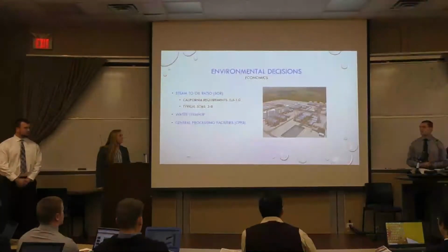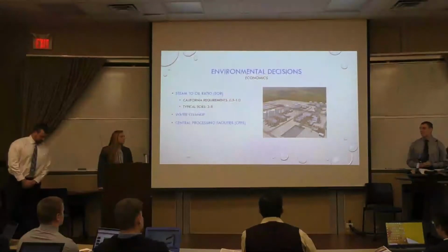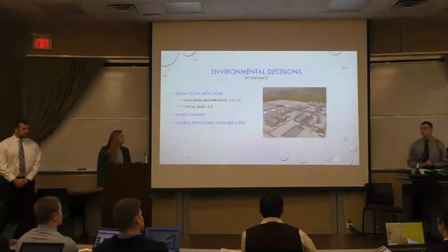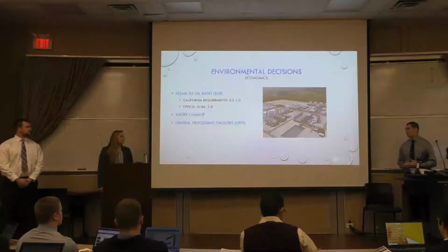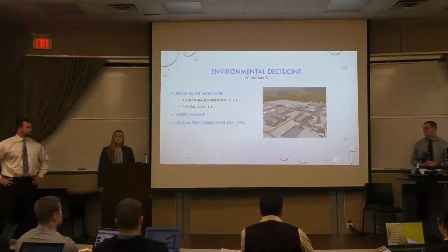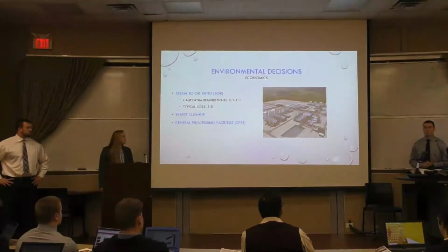It's also important to look at water. Not only the cost to inject water, but the cost to clean it once you get it back, which is kind of a backdoor cost there. Nowadays, even if you're using dirty water to begin with or slick water, you're seeing 50 cents to 80 cents per barrel to clean that up at the end, which adds up when you're injecting massive amounts.